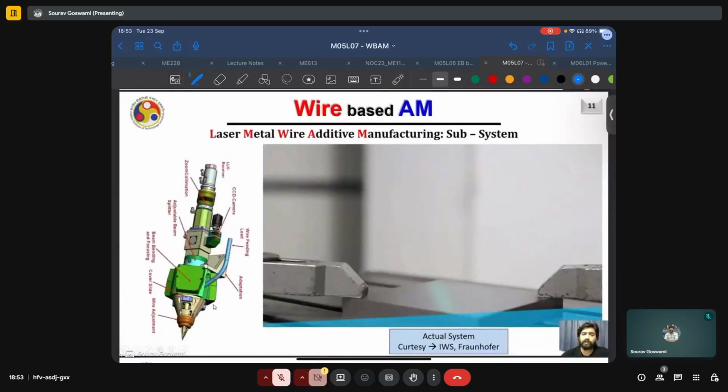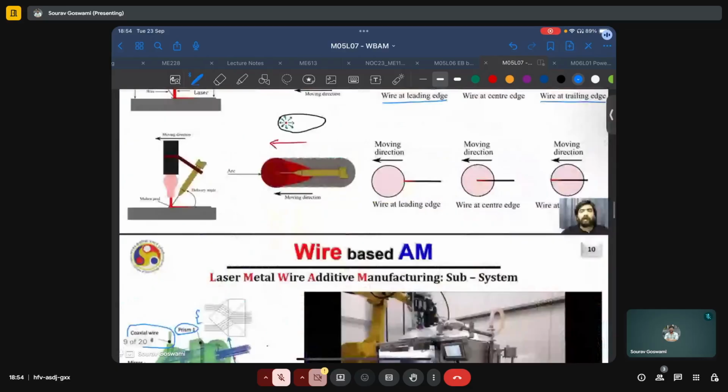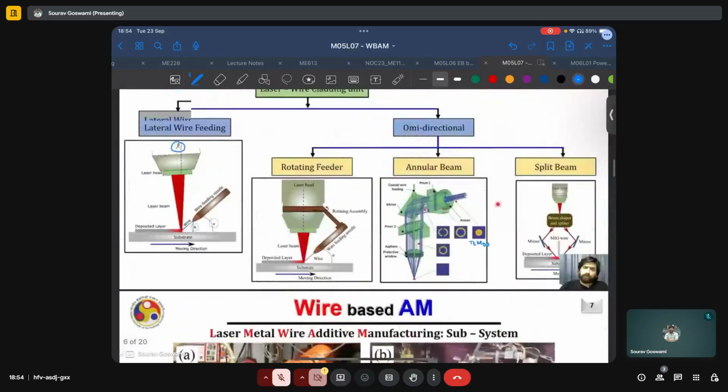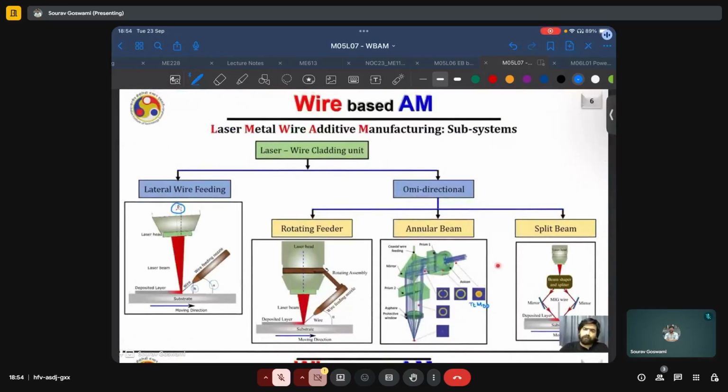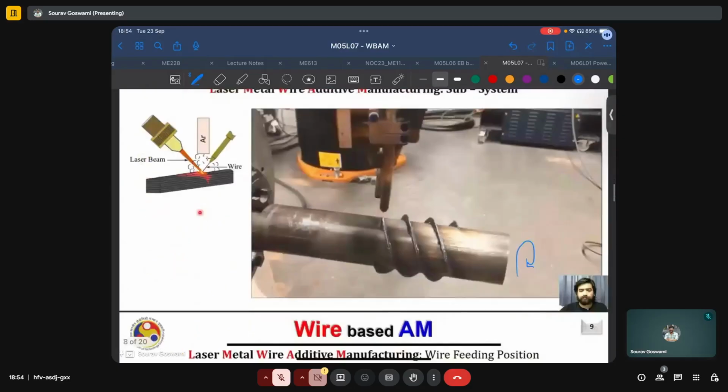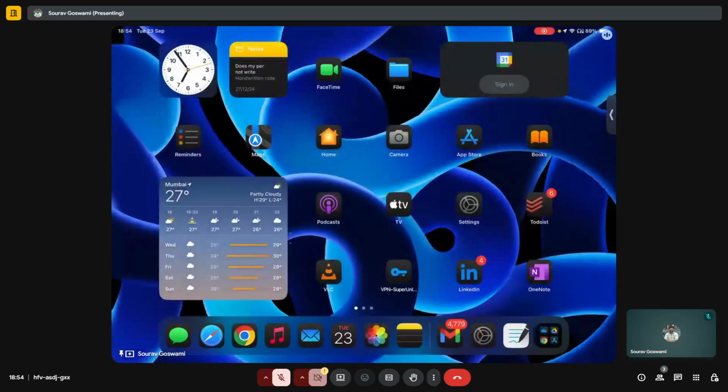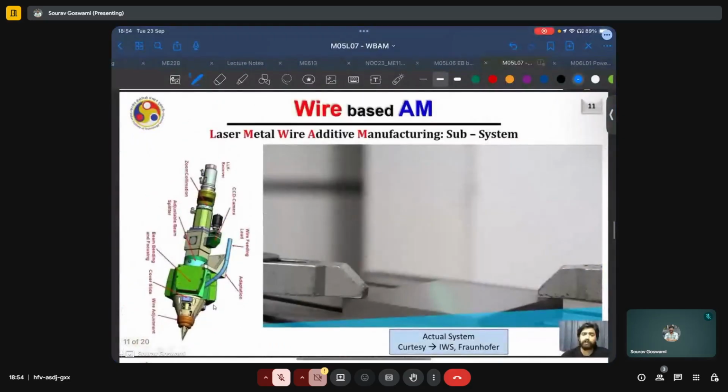A second system, which is maybe a simplification of this one, and comes with much simpler optics and consequently, I presume, a lower cost, is one where instead of having a donut shaped beam profile, we just split the beam into several discrete beams and then join them together onto the substrate surface using mirrors, which we saw in the video courtesy of Fraunhofer.